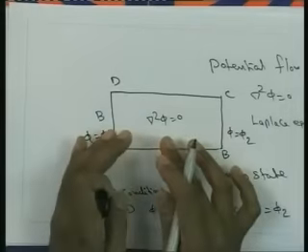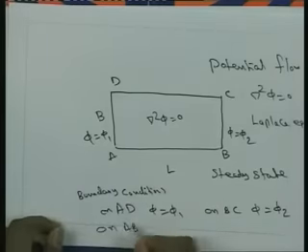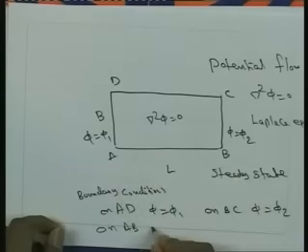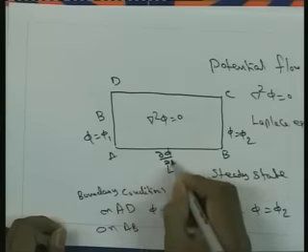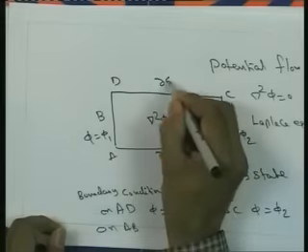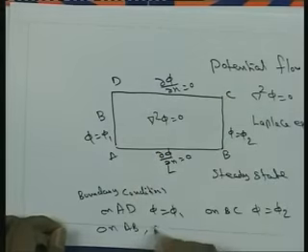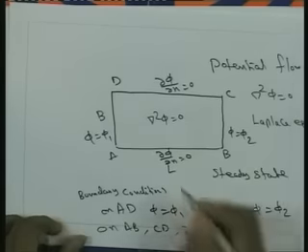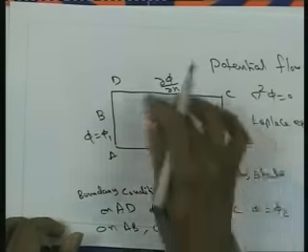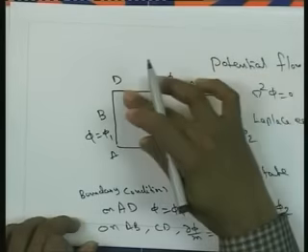Now the governing equations are known, the boundary conditions are known, and on boundary AB, if we know the variation or the flux, del phi by del n, say it is equal to 0 on the boundary AB, and on CD here del phi by del n is equal to 0. That means a no flow boundary condition on AB and CD. The flux cannot cross, that means the sides AB and CD are impermeable in nature.